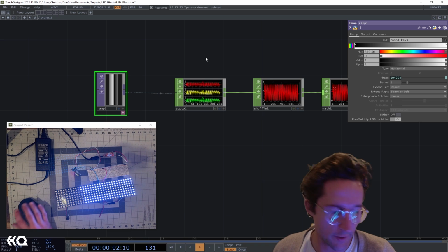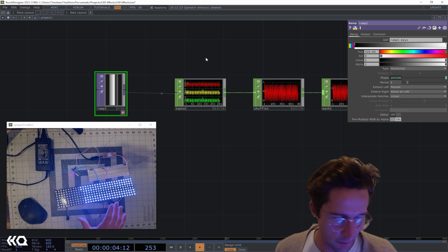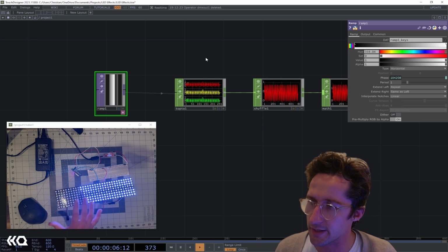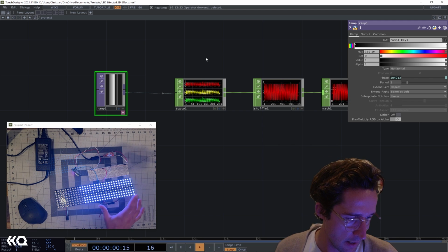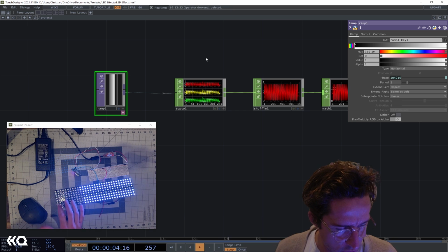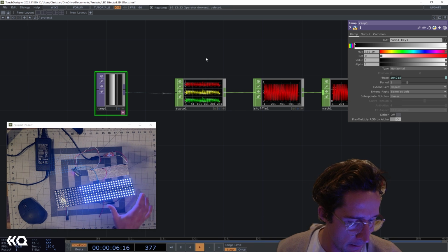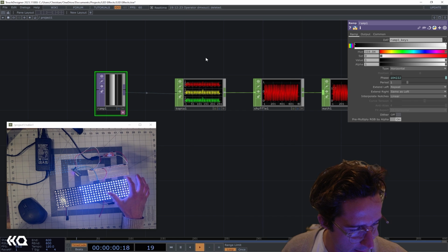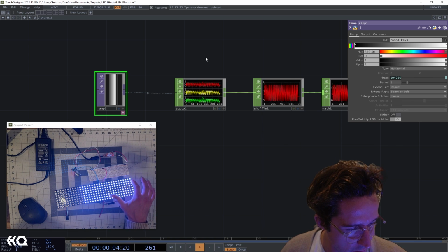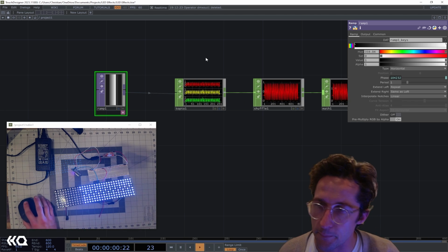And so we can see things are appearing, but there's a little bit of finickiness happening here. We actually have some dead pixels. Nothing's happening over here. And then the ramp isn't quite coming through. It looks like there's a serpentine pattern. That's telling us that the LED addresses in the matrix are serpentine. So we're sending a signal to the first row, but then it's switching direction on each subsequent row.